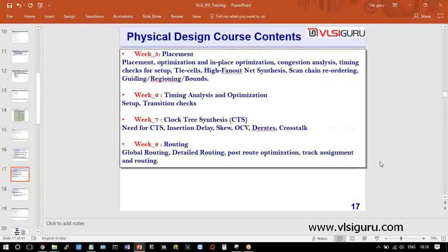Fan out again. In my design, the biggest fan out net is dash. What is the dash? The biggest net, connection between one cell to another. Which is the biggest fan out net in the design? Yes, that's correct. Clock. This is the thought that I want everybody to have: clock is the biggest fan out net. I will be giving a clock. There will be a crystal sitting outside my chip, giving me pulses. The pulses have to be taken to every cell in the design. That's the biggest high fan out net.